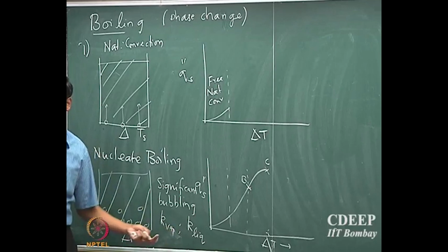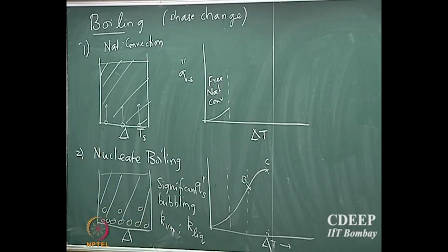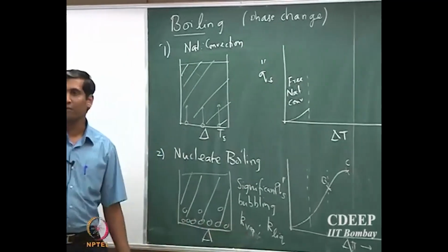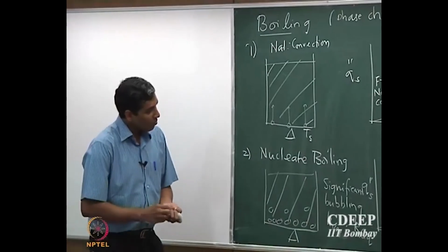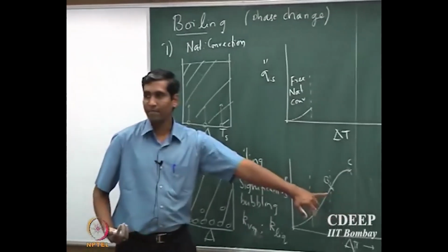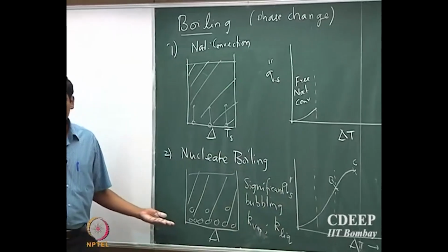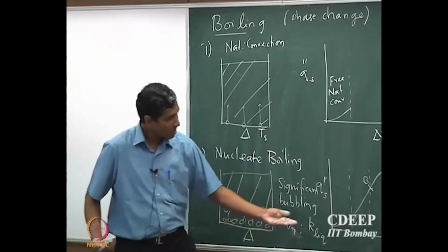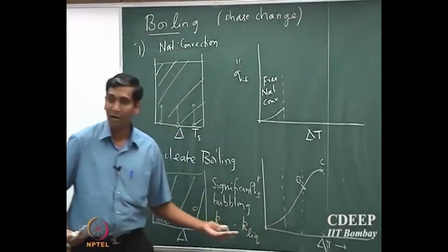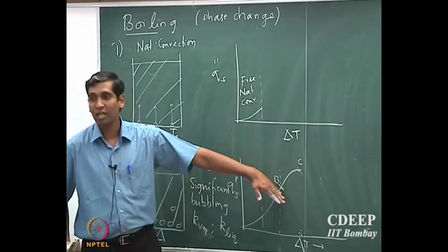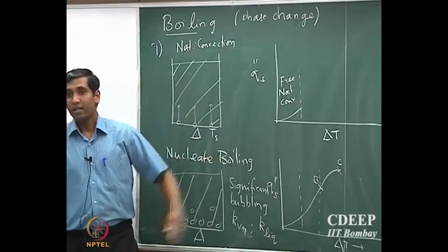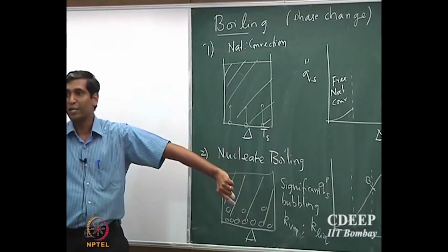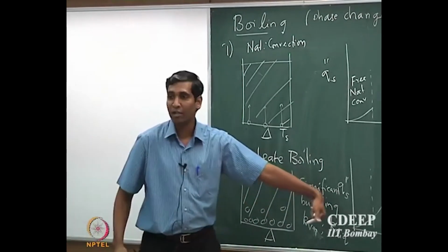Now, what is the nature of the conductivity of the vapor phase compared to liquid? It is always lower, right. So the conductivity of the vapor phase is always lower than the conductivity of the liquid. Till the inflection point, still the majority of the energy is carried by the liquid phase, and therefore, the heat transport coefficient will continue to increase all the way up to the inflection point, till the situation where there is a switch in the extent of heat transported by the liquid or the vapor phase.